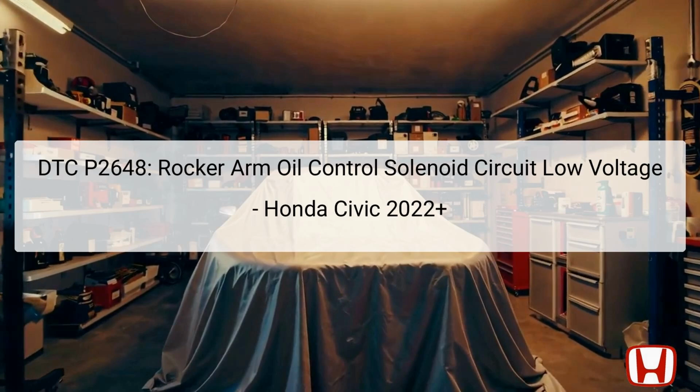The Diagnostic Trouble Code, DTC P2648, indicates a low voltage issue in the rocker arm oil control solenoid circuit of the Honda Civic models 2022 and later. This code specifically points to the rocker arm oil control solenoid, which plays a crucial role in the variable valve timing (VVT) system by regulating oil pressure for the rocker arms.